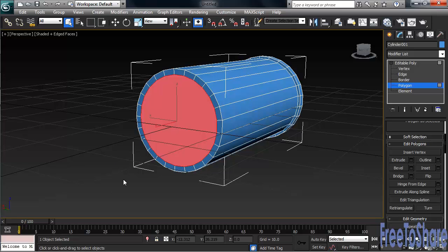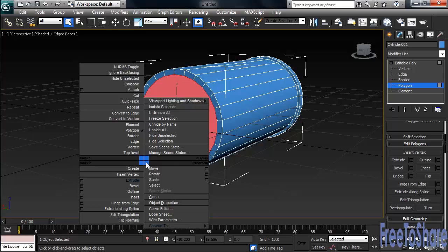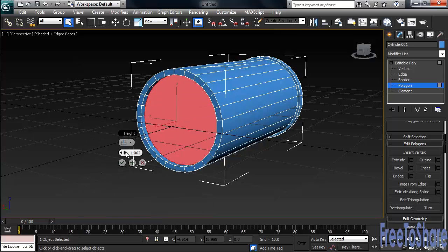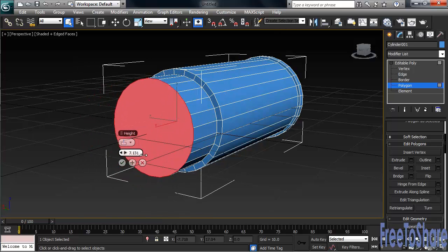Now we're going to want to extrude out the next section of our telescope. For that, we'll again use the option box for the extrude, but this time around we'll simply right-click on our screen. In the lower left-hand square, find the Extrude command, then click on the option box to its left. We can then drop down to the third row to make our adjustment.